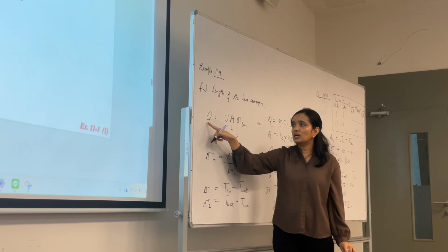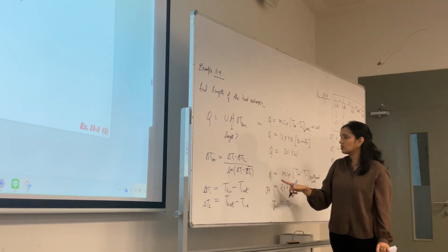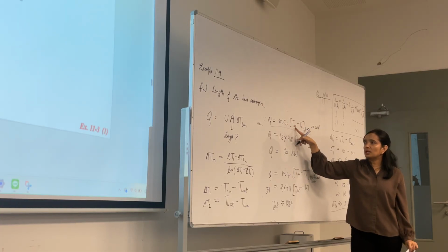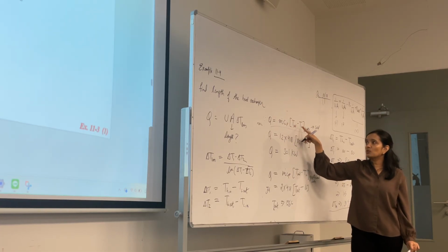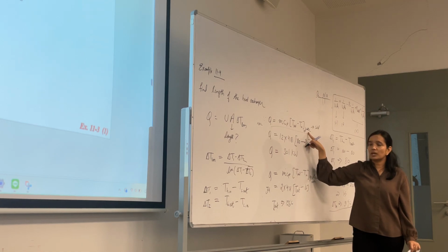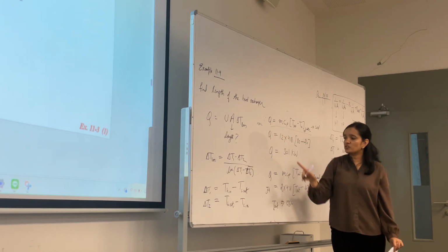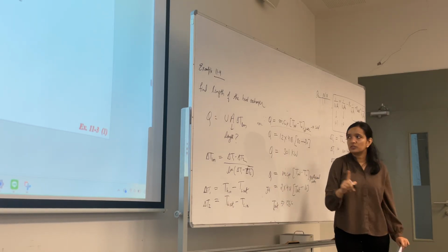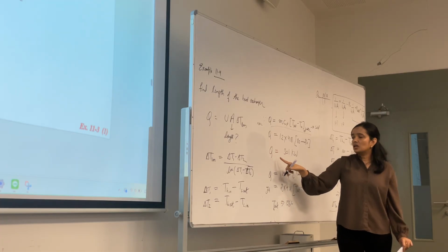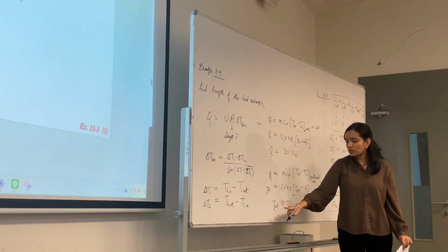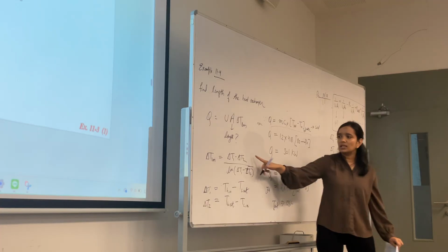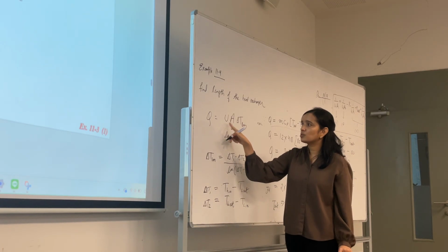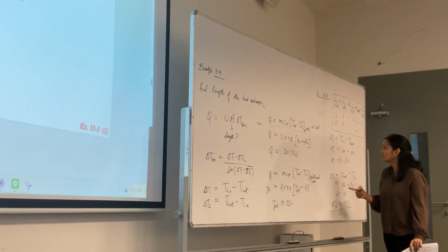Okay. So we have calculated Q from here. Mass flow rate, specific heat, temperature out, temperature cold water. This Q is the same for the cold water stream and for the hot water stream because it's a steady state. There's no transient, just like chapter 3. Once you have the Q value and the T hot out value, you can input in here, right? Now you have this value, and this value is already given in the question. You can calculate area.